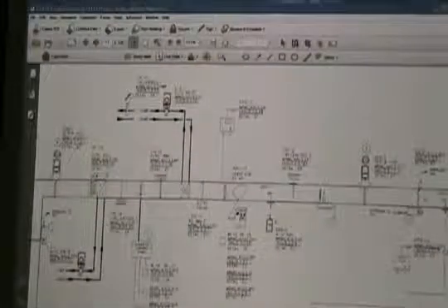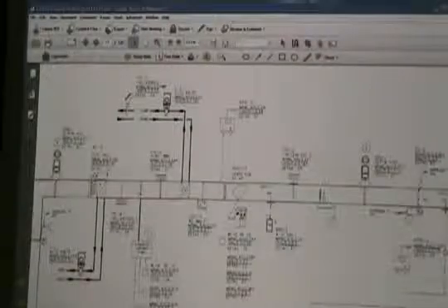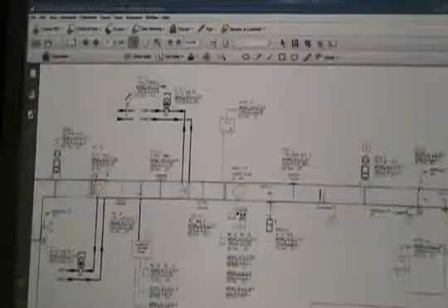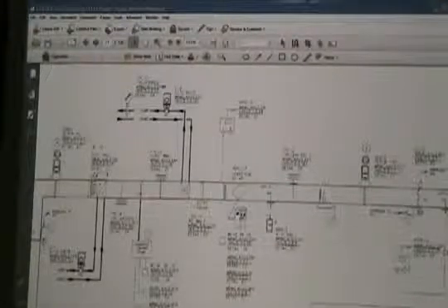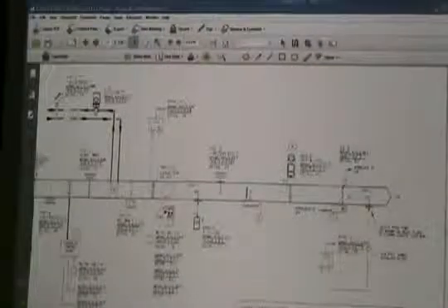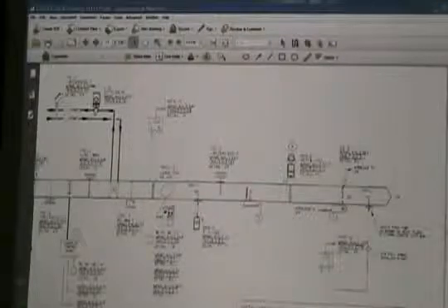Differential pressure switch, high limit, that's a safety device. Monitoring temperature, another smoke detector, filter switch. Discharge dampers, I think these are smoke dampers, probably. And the differential pressure pickup out in the duct. So we talked about a complete air handling unit and the sequence of operation.